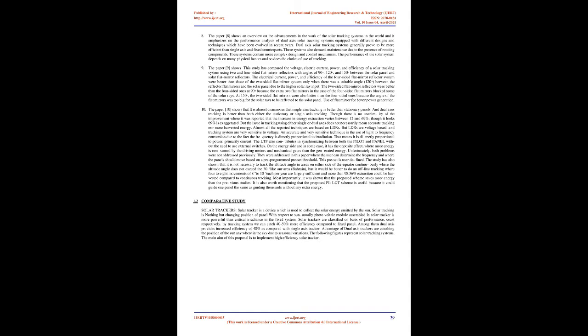Therefore, it is necessary to introduce a proportional integral derivative, PID, controller and a lead-lag phase compensator to improve the dynamic response of the system. The required specifications are to obtain a faster response with the minimum peak overshoot, Mp. The closed-loop system is initially built in the Simulink/MATLAB package and the PID controller and lead-lag phase compensator have been built into a special subsystem. The components of the control system have been dragged directly from the Simulink library. Results showed that when the compensator is properly designed the response would be acceptable in the sense of required specifications.